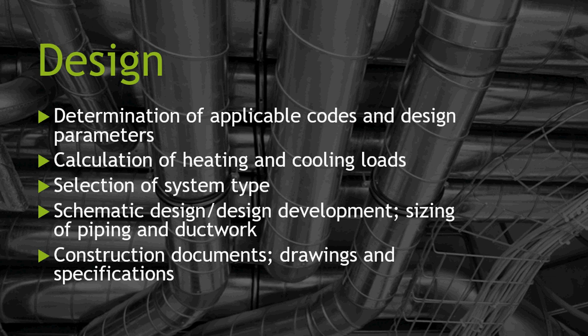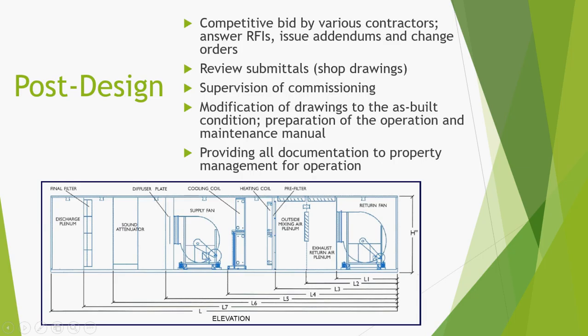In a design bid project, the construction documents are what the contractor uses to bid a project. The documents usually consist of drawings and book specifications. The specifications detail all the equipment and material standards and how the contractor should install them. When the construction documents are complete, they are sent out for bid. The design bid process allows multiple contractors to bid, which keeps the prices low and competitive.